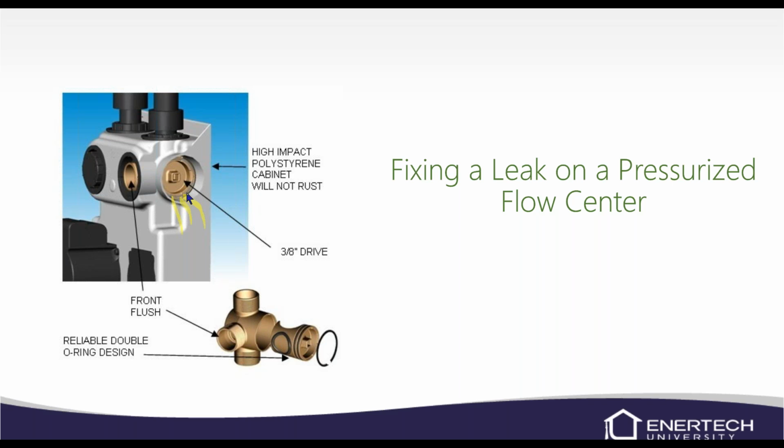I will say that if those seals are an issue, you probably have a water quality issue. And so we'll probably have to check that water, because what's happened is it's eating away at these Teflon gaskets that are in there. There are 3 of them. There's this round one on the side down here, and there are 2 on the end of that valve there. Basically, there's a snap ring. If you remove the snap ring that's located there, then you can put a little square drive on that and just move it back and forth while you're pulling a little bit, and you can slide that whole piece out.